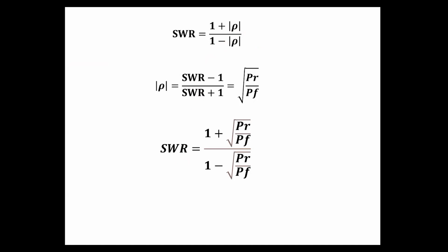Okay. So the voltage standing wave ratio is the ratio of the maximum peak voltage anywhere on the line to the minimum value anywhere along the line for a lossless transmission line that's at least a quarter of a wavelength long. The ratio of maximum to minimum current, or ISWR, is identical to the VSWR. This reflection coefficient is the ratio of the voltage or current in the reflected wave at any one point to the voltage or current in the forward wave at that same point. And it's a complex quantity. That means it's got real and imaginary parts. It's got resistive and reactive parts to it.